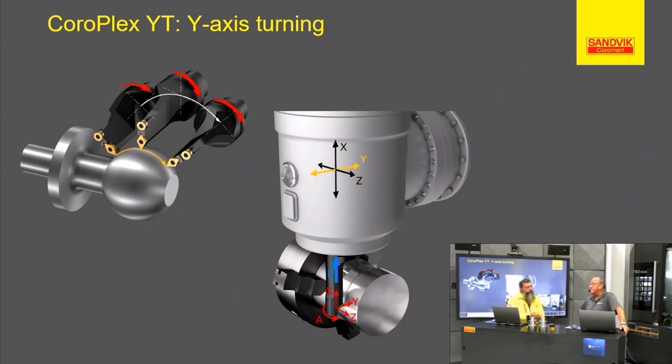Well, definitely the rigidity of the tool and the design, actually the way it is built. It's a combination of inserts that you're actually using here, and we will see this shortly. I love that when we turn in the Y-axis, the insert is pointing down. So basically all the chips that are being cut shoot right down into the chip pan and don't get wrapped around somewhere else. There are a lot of benefits in those tools, and the rigidity is amazing.